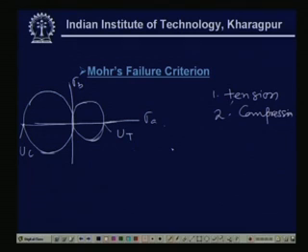So, this is UC. Why is this UC larger? The same logic: compression test results normally give a larger value compared to what we get in the tensile tests. So we understand that any stress level within this will always give you a safe result. And this particular result, if we try to put it in a graphical manner, then what do we get?